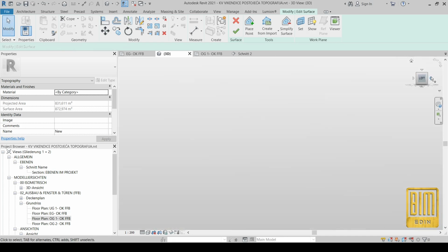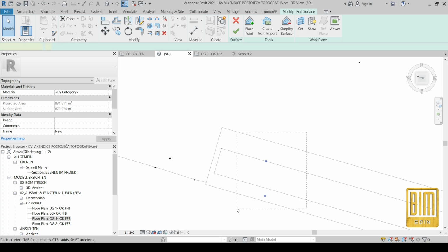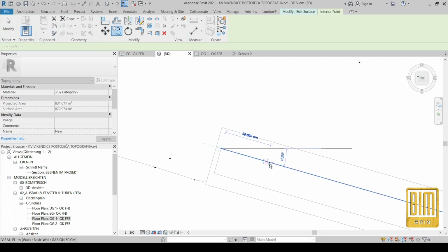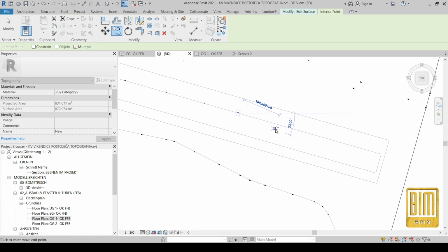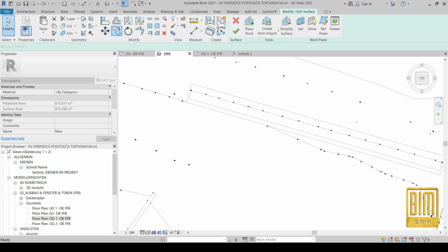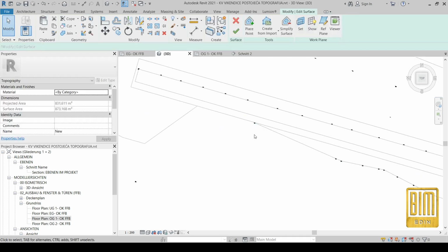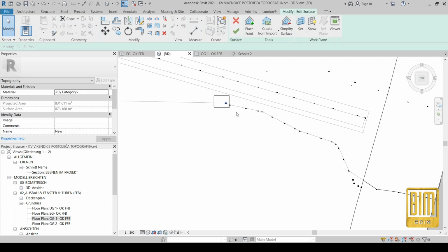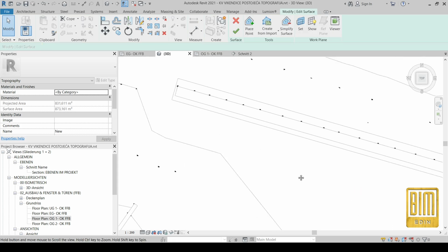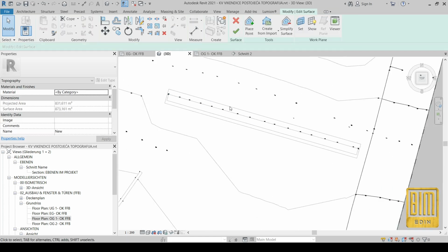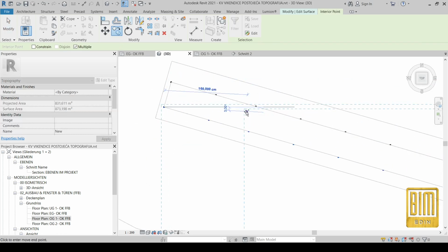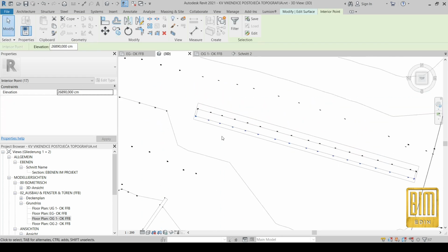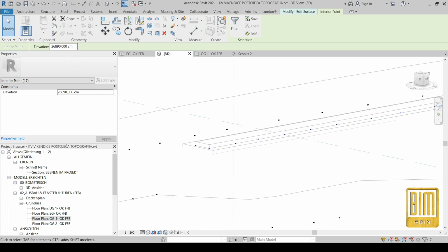Now you can see I align this point to this reference level. The reason why I created this reference level is that I want these points to be lower 10 centimeters from the top of this gabion wall. And as I said before, this method is more important if you have sloped angle on this gabion wall. So our reference element will be angled, and we will join it to wall, and that join line will be our reference line where we're going to align these topography points using align tool.